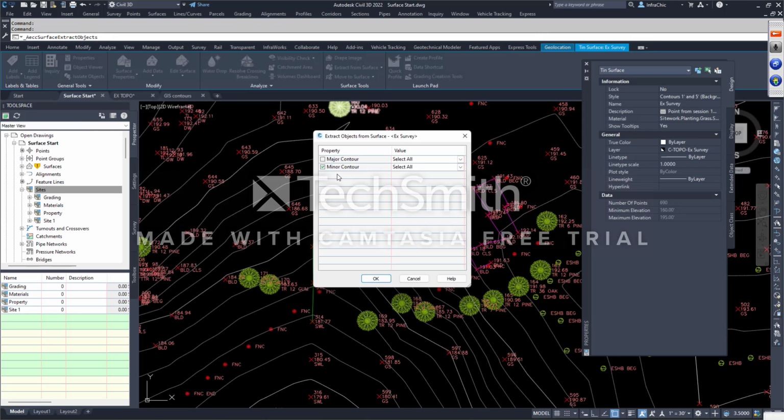And if it's an uneven number and you figured out what it is, 677.32, or in this case, maybe it's 184.25, what you want to do is adjust your surface style contours to show 0.25 foot elevations. Find that specific contour, 184.25, then do extract object, select the minor because it's 184.25. Don't tell it to do every single contour you got. Do the drop down and select the contour from the drawing. Then you get the pick in drawing button or select from drawing button.